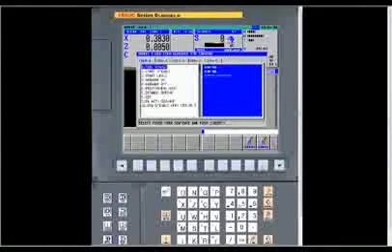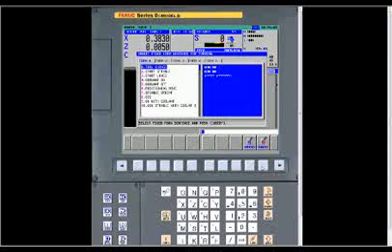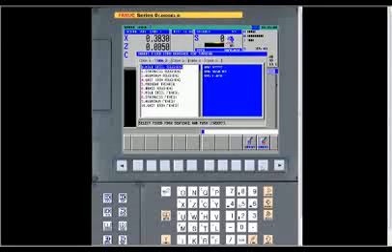So now at this point, what we want to do, we want to call up a cut speed for the material that we're going to cut. And the material we're going to use, this is 4142 preheat treated material. And most all of you are going to understand what that is. And let's see, I have a selection for preheat treated roughing cut speed.